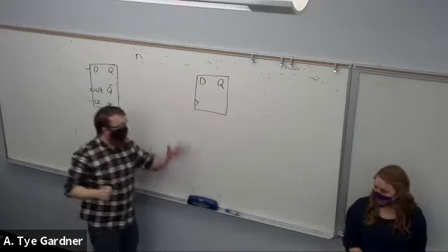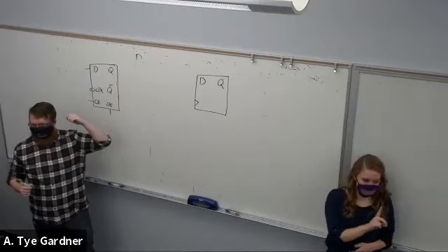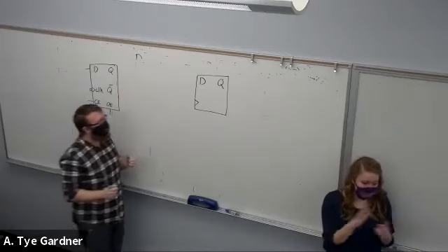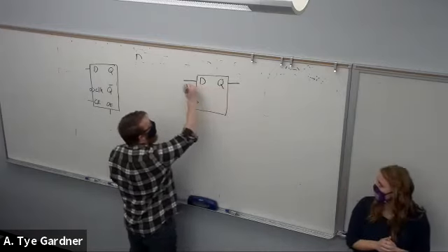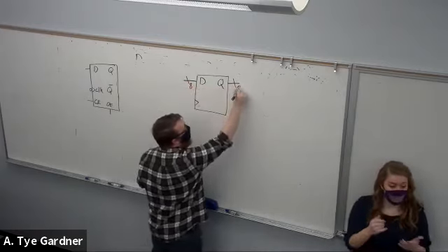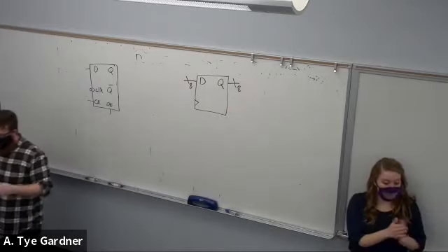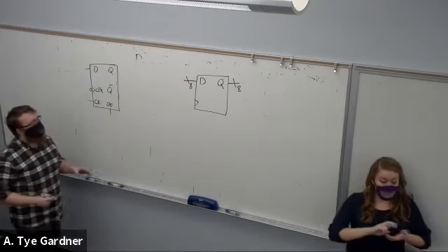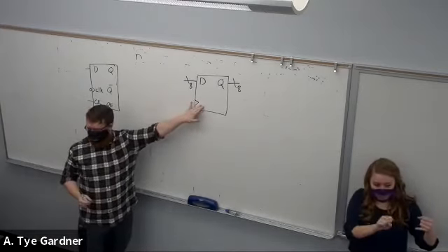So this is the simplest way that I can draw a D flip-flop, right? There's no options on it. I didn't bother labeling the clock. It's still a D flip-flop. But I've used this notation before in lab where I turn this into a bus. Now the implication here is that there are 8 wires going into one D flip-flop.